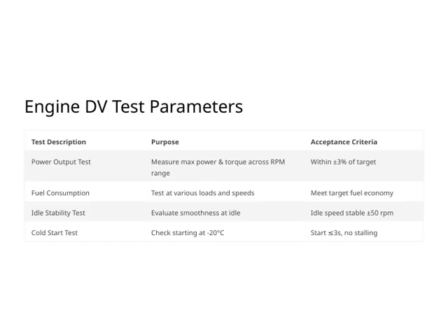We evaluate how the engine performs at different loads and speeds to verify that it meets the targeted fuel economy. This helps us confirm the engine's efficiency in real-world scenarios. The idle stability test assesses how smoothly the engine runs when idling.